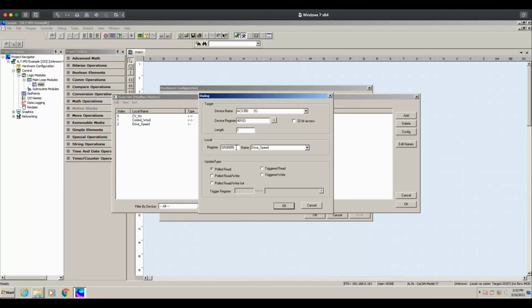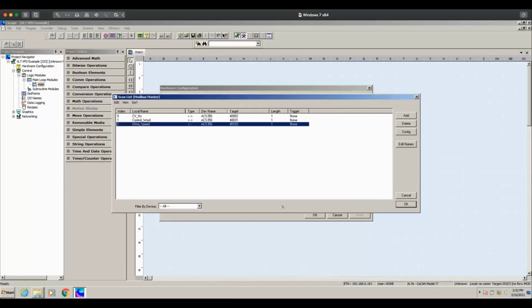And if there's some information in the middle of that group of 16 that I don't care about, then fine, I'll ignore it. But maybe there's 7 or 8 parameters I do care about, and I can access them all in this one read command, one entry on the scan list. So that's what's required from a scan list standpoint for configuring what data the OCS is going to be polling on a regular basis.